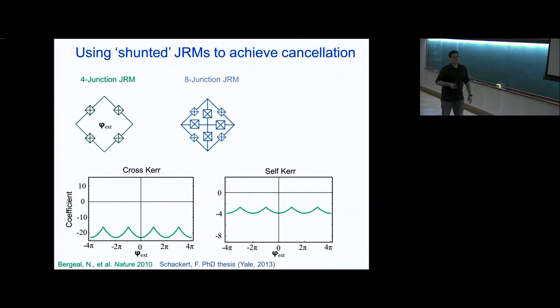So then the way we made them in our laboratory for a long time, because it's easy, is to put Josephson junctions here in the middle. And this has some nice engineering properties. It makes the device tune more easily. It's just a more practical circuit. That one, at first, looks good, because you see here now, because of the effect of these shunts on the overall stability of these now four loops, you can stay on this primary flux configuration until you reach the null. And this looks good until you look at the self-curve of the modes. Basically, these extra junctions add extra nonlinearity. They push you to a very negative starting place, and you basically never make it to the cross. So you can kill some of the Kerr terms, but not all of them. This basically is no help. These terms typically are about the same size. Killing some of them just leaves the other ones basically right where they are.